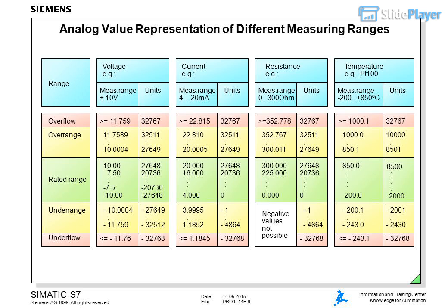Sensor, temperature range, rated range when encoded. PT 100: minus 200 to plus 850 degrees Celsius, minus 2000 to plus 8500. Ni 100: minus 60 to plus 250 degrees Celsius, minus 600 to plus 2500. Thermocouple type K: minus 270 to plus 1372 degrees Celsius, minus 2700 to plus 13720. Thermocouple type N: minus 270 to plus 1300 degrees Celsius, minus 2700 to plus 13000.